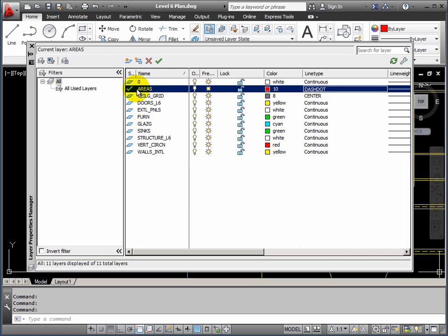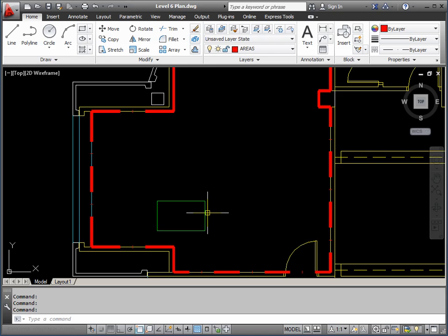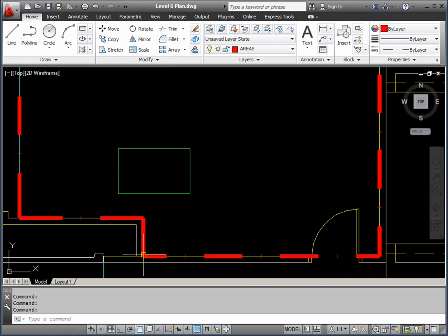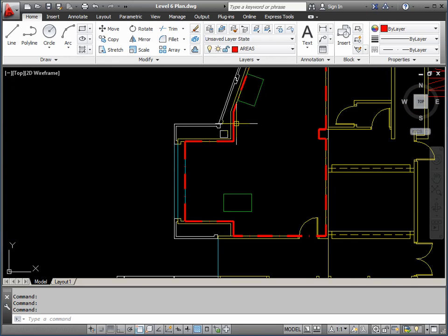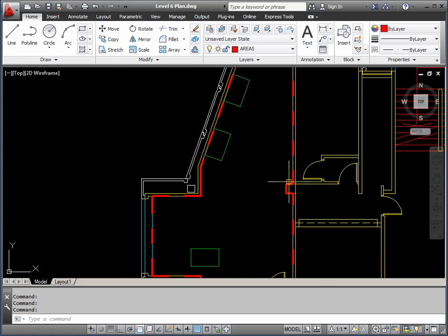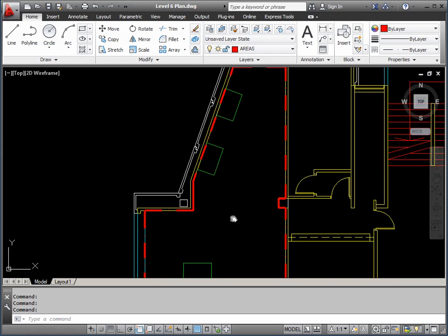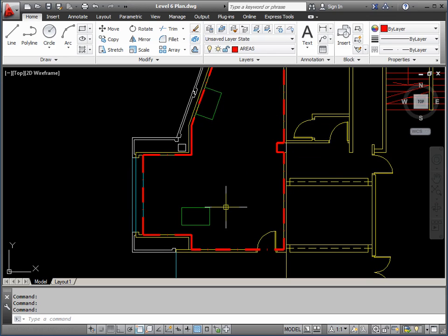Okay, so the layer now has a different line type than the rest. Close the dialog box, and we can see that the layer is now showing different line type. Okay, when it gets to short sections of line, it's struggling. It isn't able to show the dashes and the breaks around these. So there's no breaks in that bit, there's nothing around the column. So if I had a very short line, or a line that was changing direction regularly, that could be a problem.